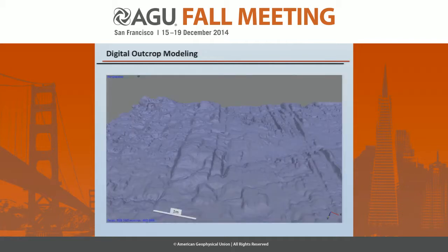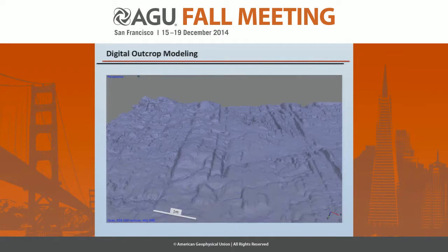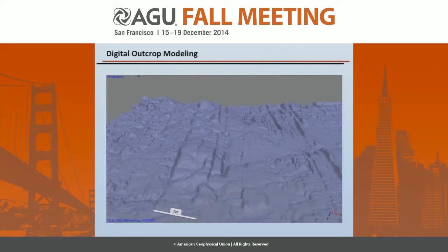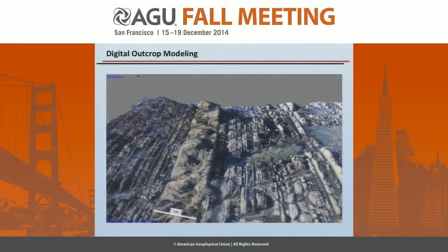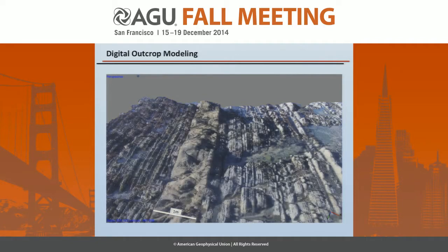So to drive this point home, the digital elevation model that's created, just the filled in, can really be best viewed and then further interpreted, even in the comfort of your own office, once that imagery or orthophoto generated by structure from motion software is draped over top of it. If the images are tied to ground control points, then the final result is a fully georeferenced high-resolution photorealistic DEM.